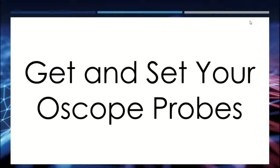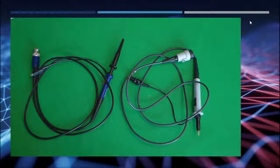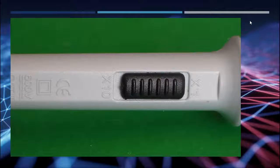When working with an oscilloscope, it is important to have good oscilloscope probes. For this video, I will use 2 oscilloscope probes, and here are my 2 oscilloscope probes that I will be using. On your typical oscilloscope probe, there will be a switch that allows you to switch from X1 to an X10 setting. We will explain what this means a little bit later.